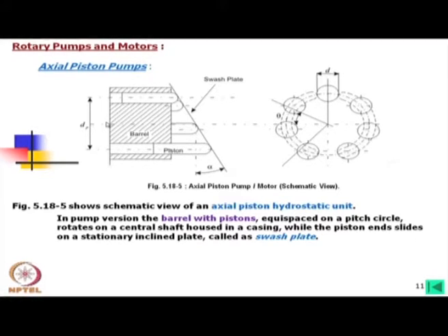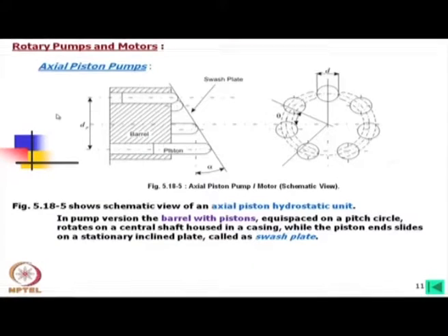And between this barrel and swash plate there is a spring, so that with a high pressure this barrel is in contact with the valve plate. We shall again discuss the details of such pumps in another lecture. So, let me explain only this much, that oil is going out through this side and there are also kidney ports. I mean, kidney type ports are used also for this type of pumps.